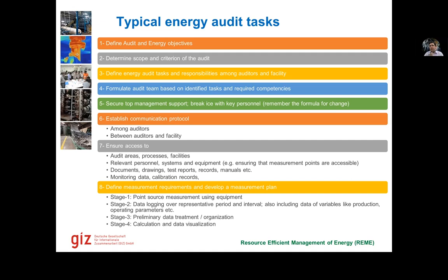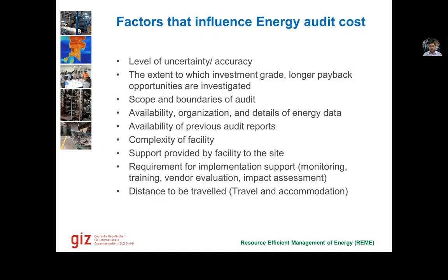So rather than inserting the probe once and only measuring the point source emissions, we could install a data logger there, which could take profile of 2, 3, 4 days, and for the same time we could have the production data as well, and then we could make energy performance indicators. Stage 3 would be then to organize this data, analyze the data, identifying the areas of improvement, and then doing the calculations and data visualizations in stage 4.